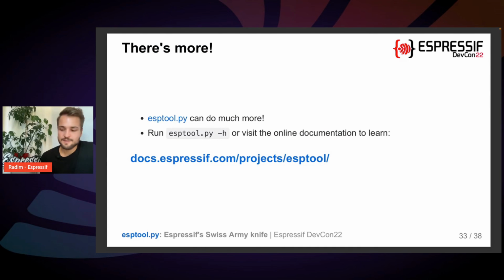This was just scratching the surface of what esptool.py can do for you. It can do much more. So you can just run esptool.py -h, like help, or visit the online documentation to learn at docs.espressif.com/projects/esptool. There's a lot to learn, and it gives you great power when you know what to do.